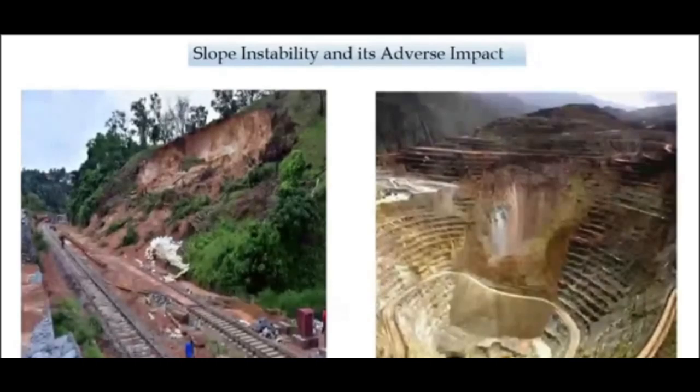When we are dumping such material, or going for such a configuration as shown on the right hand side of the figure, again we need to be very sure about how those slopes are going to behave, because any failure or instability in the case of mines will not only have an adverse impact on the mining operations, but sometimes on the machinery, and in some unfortunate conditions you may even have loss of lives, which is not at all desirable. So this is where slope stability comes into the picture, and right now I have tried to restrict my discussion to strata or ground conditions which are mostly rocky in nature.